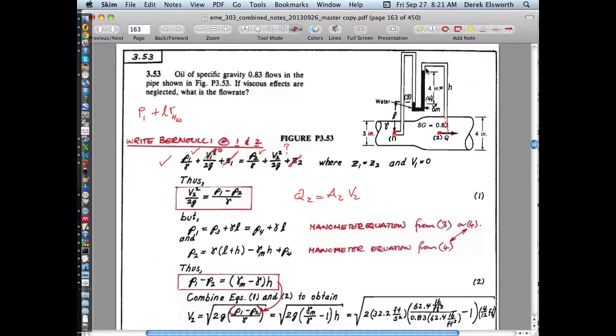So to go up to this point here, this is negative, this is minus, right? Pressure here, you go up, you subtract, you end up here. Simply connected fluid, you end up at this point here. You can go up another 4 inches, and that's subtracted. Minus H, I think this is 4 inches, equals H times the unit weight of the gauge fluid, which I think is mercury in this case, but not sure. And then you end up at this point, and then you have to come down all the way to this point. And so this is going to be H plus L.